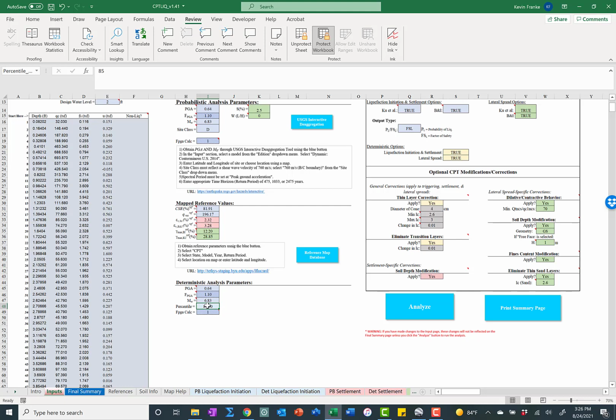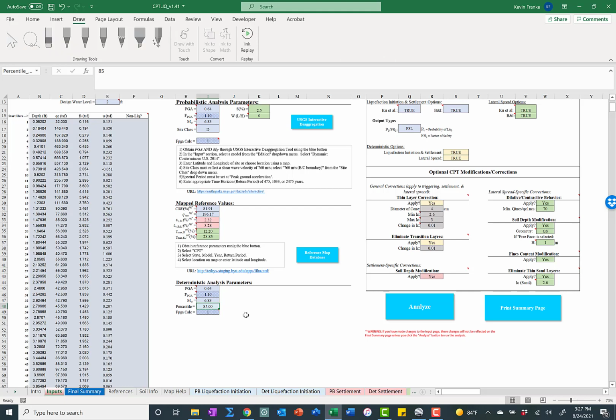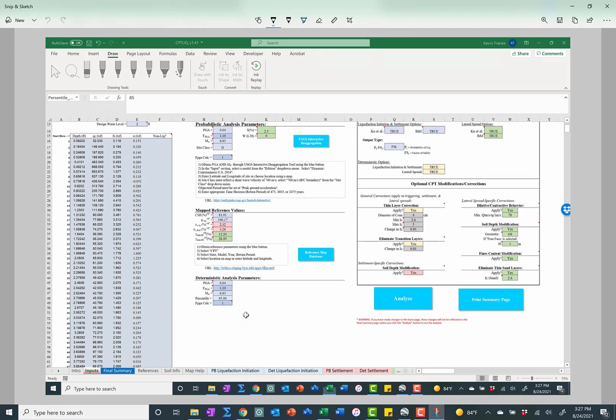Okay, so the deterministic, think of this as 1 minus the probability of liquefaction. Okay, it worked. Think of this as equal to 1 minus the probability of liquefaction. So if Boulanger and Idriss, for instance, say my deterministic triggering curve corresponds to a probability of liquefaction of 15%, then in that percentile you'll write 1 minus that probability of liquefaction.